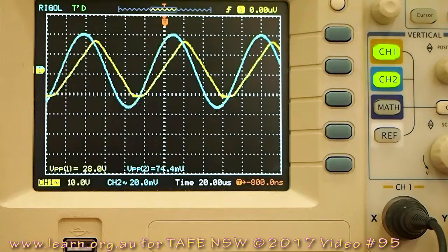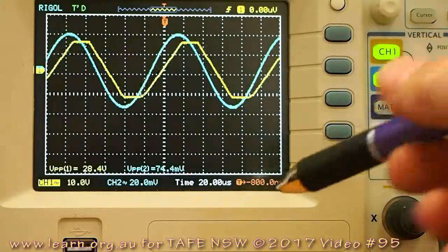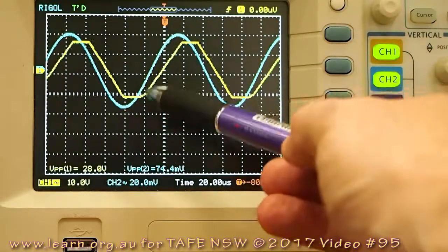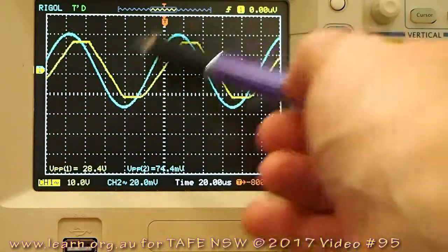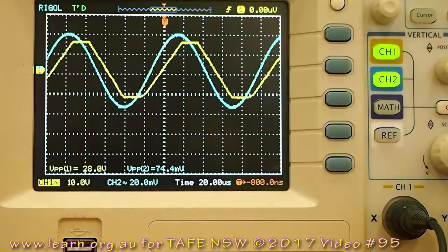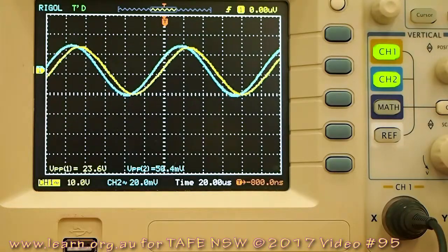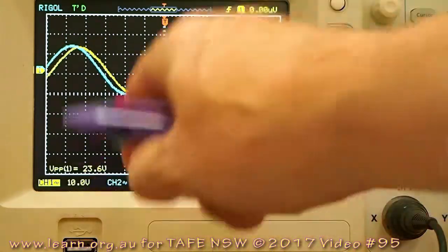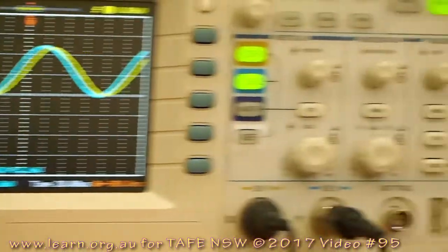And back down to 11 kilohertz, I can still see I've got distortion. Oh, now all of a sudden the amplifier's sprung back into life. It's decided that the slew rate distortion's not so bad. It's trying to do some amplification, but now I've got flat topping, so I'll have to turn that input back down again to 49 millivolts. 50 millivolts will do. I'm at 9 kilohertz now.